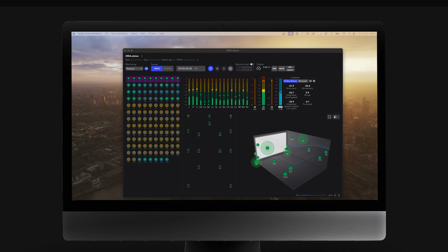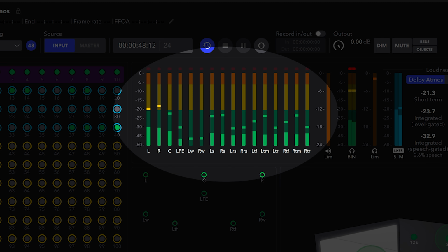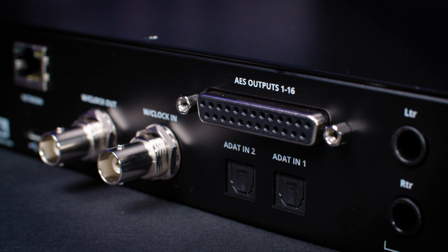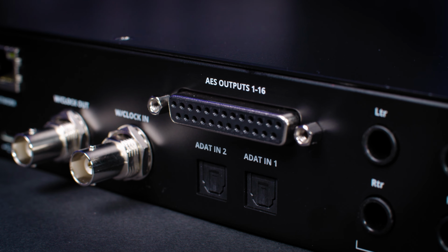The outputs on the rear panel of Auria are labelled to match the standard as defined in the Auria software app, and these also match the Dolby Renderer's standard output definitions. If using the AES outputs, make sure these are manually assigned to the correct speakers using the Auria software app before starting measurement, as the channel routing will be sent to the Measure app.